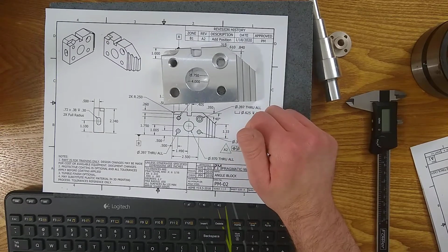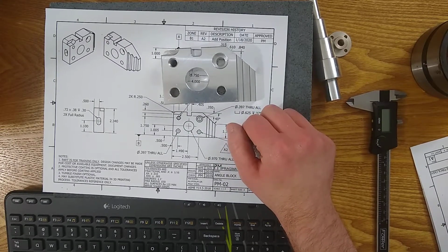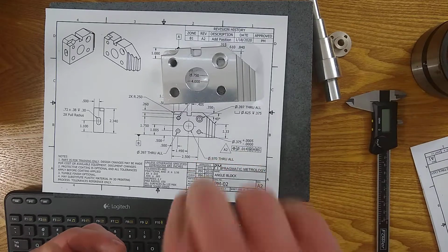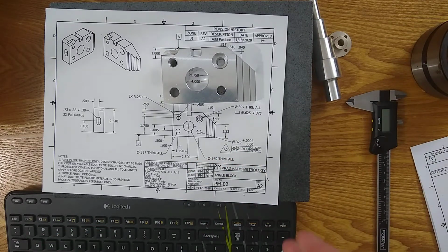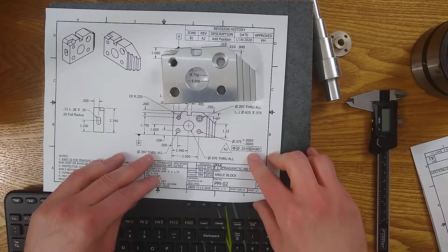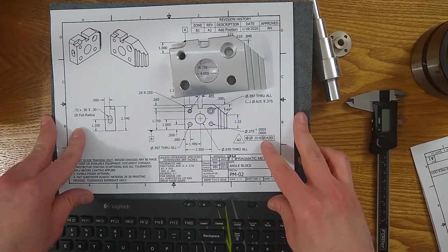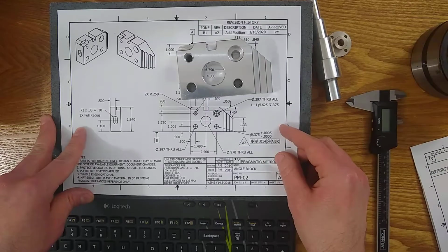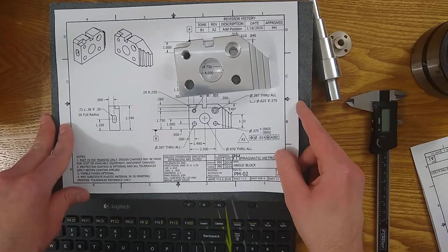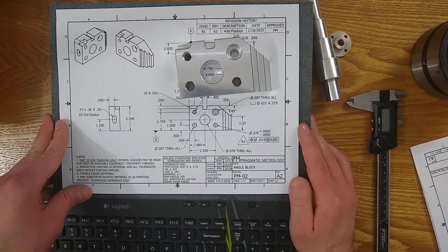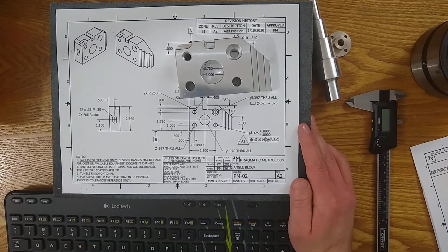Hopefully you don't have a tight tolerance, because then there's really not a better way to do it. There are some precision gauges out there that will do depth, but in most cases you don't need to use them. I've never needed to use them. I've run into a couple parts where the depth has really been important, and it's been a bear to control from a manufacturing point and from an inspection point. It's been a real pain, so we try to avoid it.